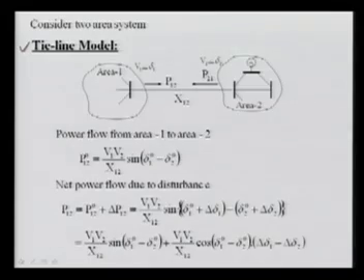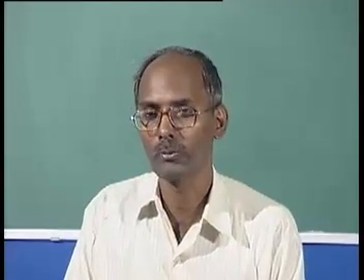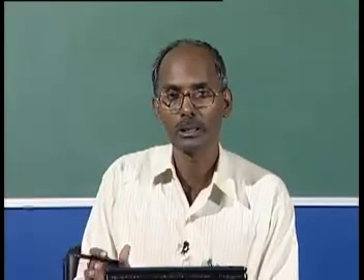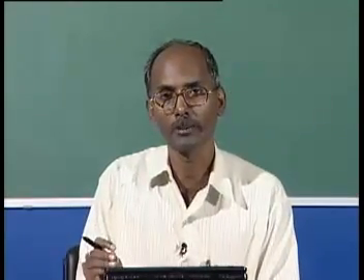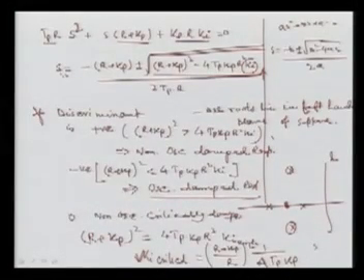So now I can recap what we did in lecture number 4. We saw that the secondary ALFC control loop was designed to remove the frequency error, and in steady state we got zero frequency error, which is required. We also saw the dynamic step response, that is, whenever there is a change in load, what the dynamics will be, and we derived that curve. And we found that the gain Ki is very, very critical.